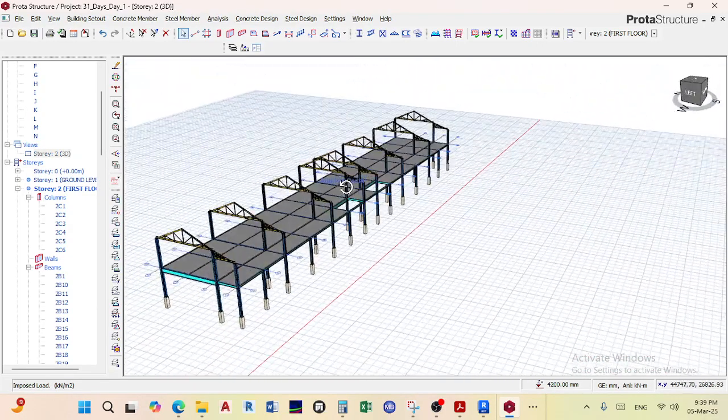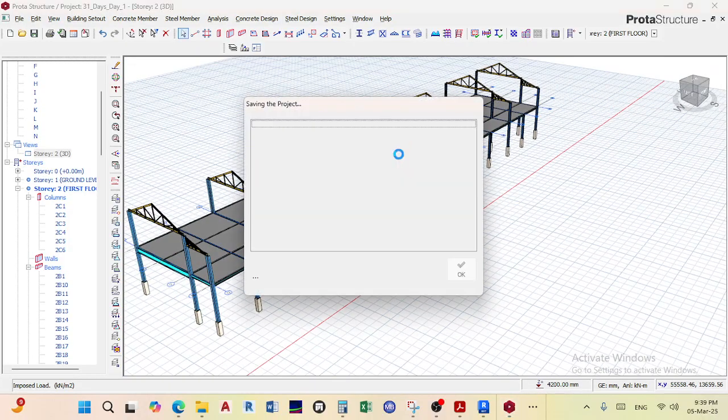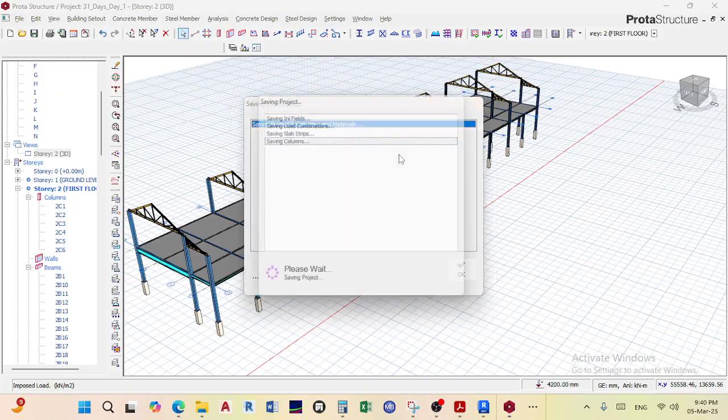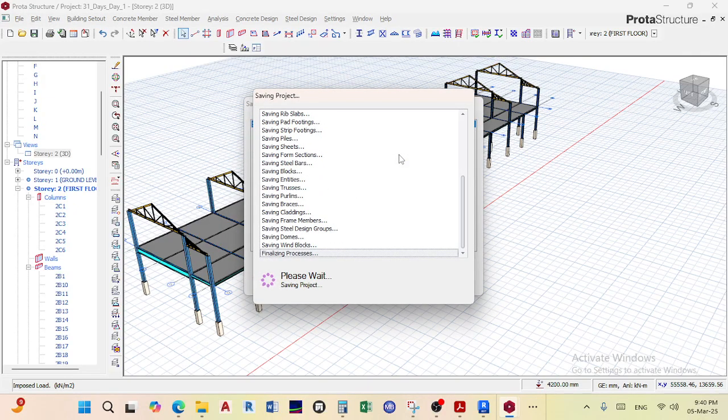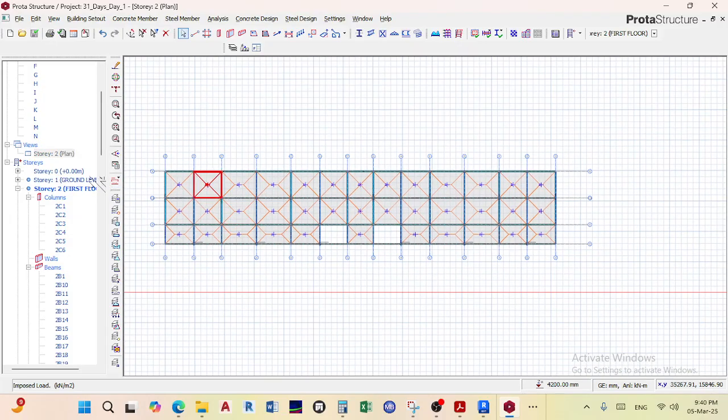You see? And then I'll press control S, and then I can add a floor also on the ground floor, also known as the slab on grade or the foundation slab, because it rests on the earth, on the grade, hence slab on grade. So when you go to ground floor, you select it, you switch to your plan view.